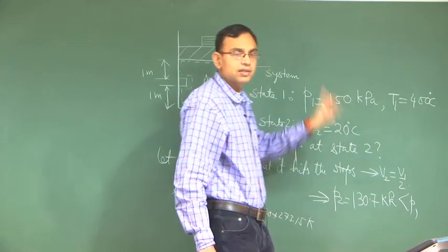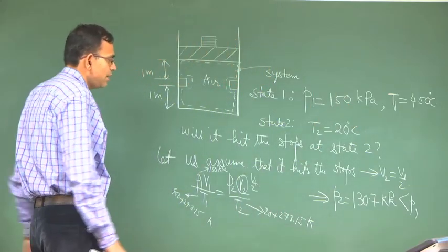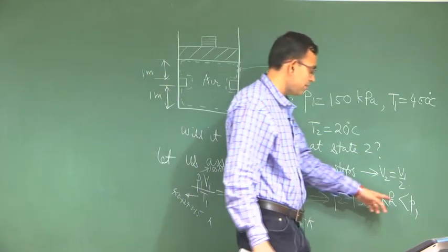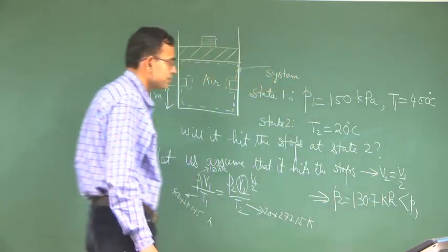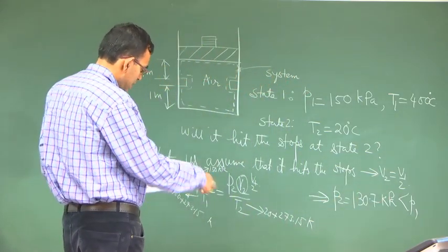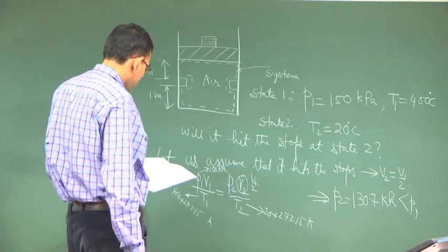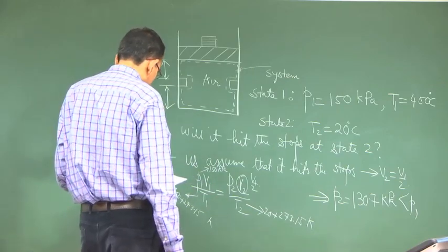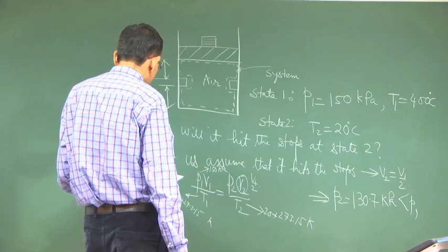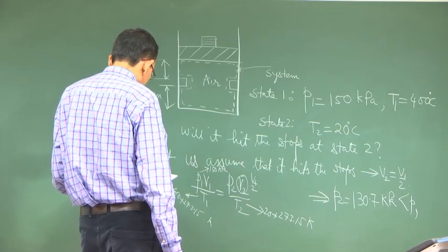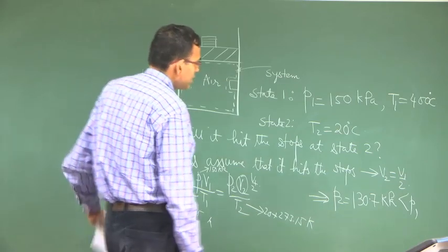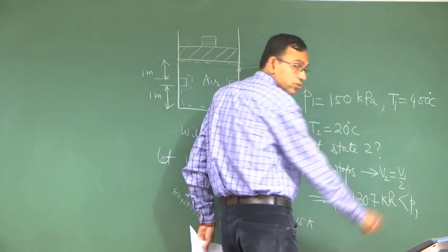Because it has not remained as 150 kilopascal and it is less than this one, that means it has hit the stops. So, the answer to the first question, is the piston resting on the stops in the final state, is yes, and this is the pressure at state 2.